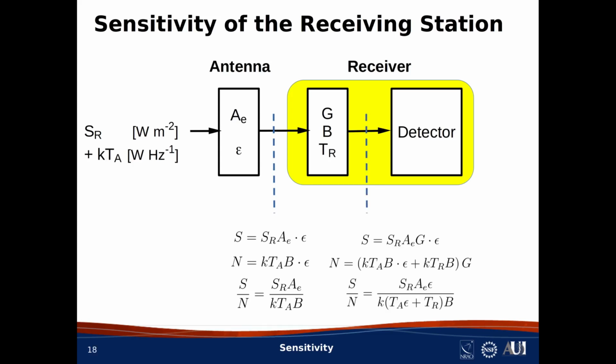And here's what's happening at the input of the detector. S is increased by the receiver gain, G, as expected. N gets an additional term representing the internal noise of the receiver, and then the sum of those two noise terms goes up by a factor G by passing through the receiver. So, for pre-detection signal-noise ratio, we get the expression now shown in the lower right. Note what's happened here.